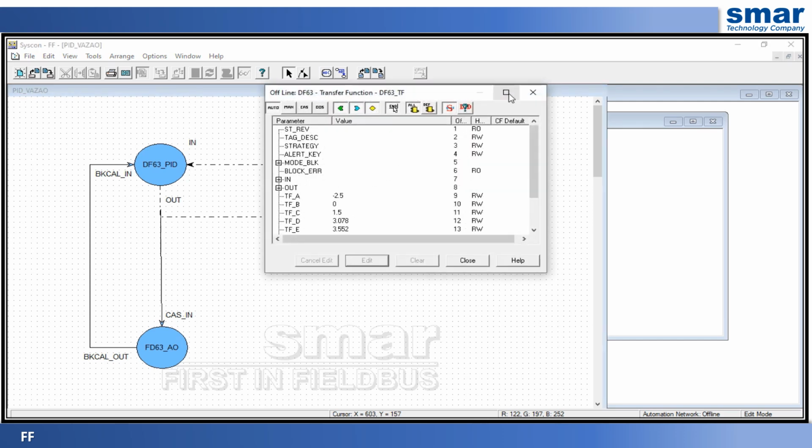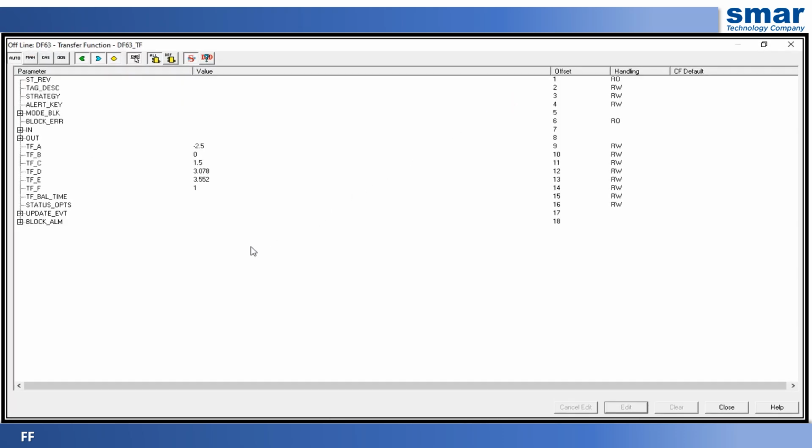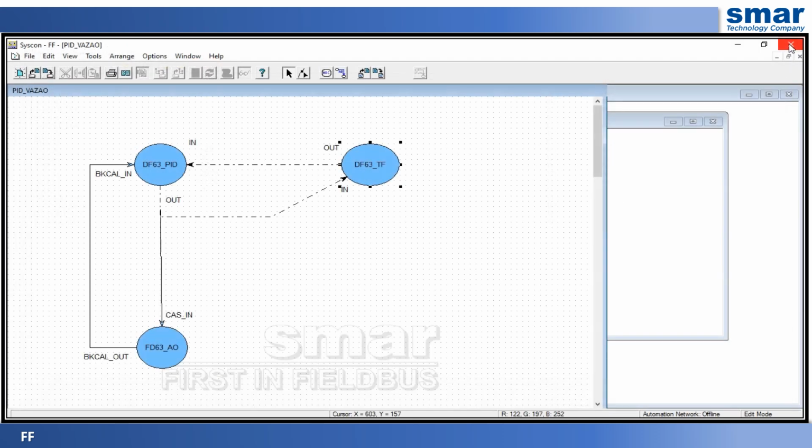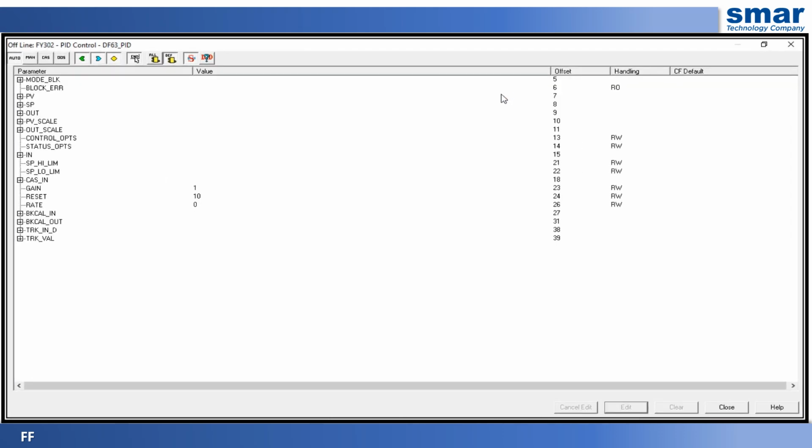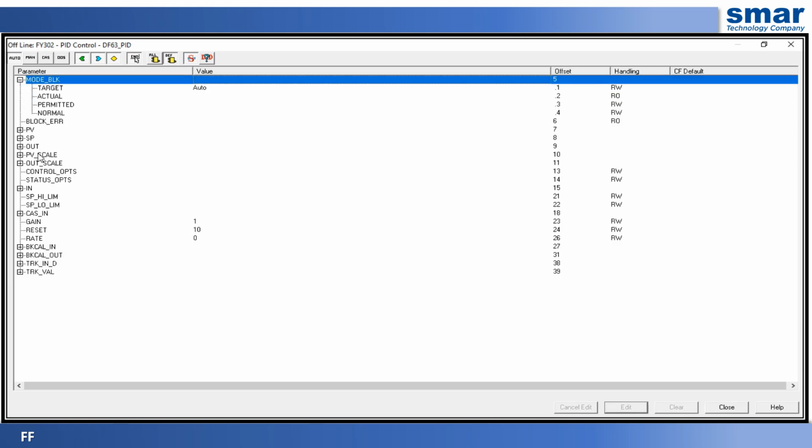We can observe the parameters entered to simulate the strategy, the transfer function block. We will guarantee that our control loop functions automatically and provides a prompt response. Send the signal to the PID. The PID will run in automatic mode. We applied a preliminary tuning, a gain of 1 and 10 proportional.